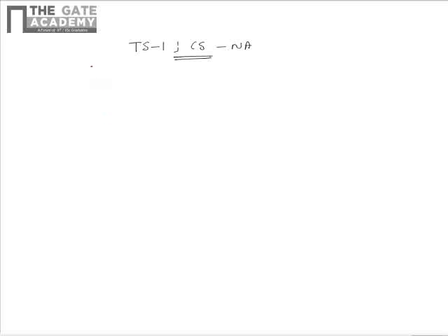As per the question, the open loop transfer function of a unity negative feedback control system is given as G(s)H(s) = 100(s - 5) / (s(s + 10)). We need to find the phase crossover frequency of the control system.